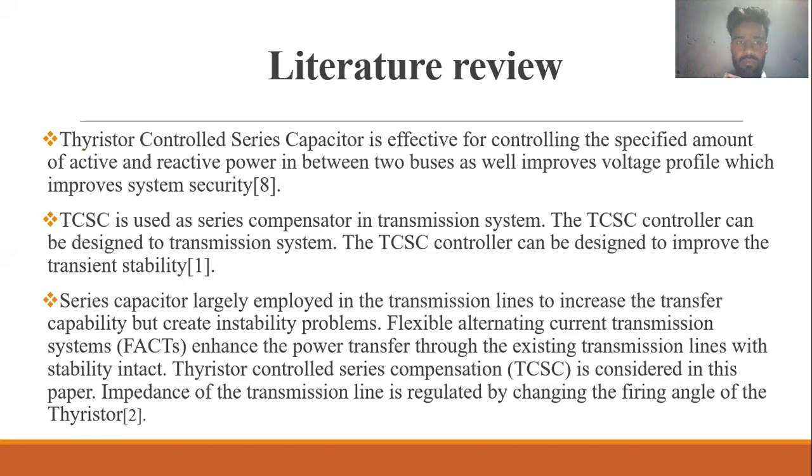Moving ahead to the literature review, in the first paper we studied how the thyristor controlled series compensator has a controlling mechanism with a specified amount of active and reactive power compensation. In the next paper we studied the series compensation of the transmission system by controlling TCSC and transmission system design. Also we studied its capability to improve the transient stability of the power system.